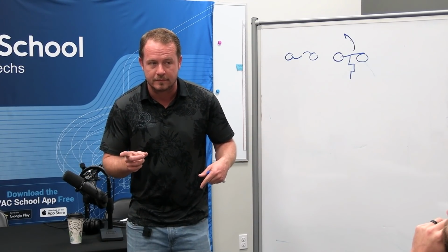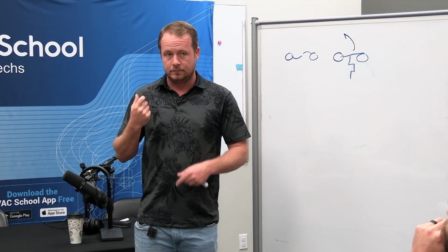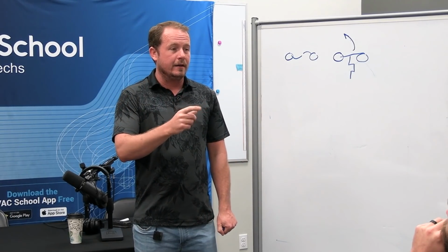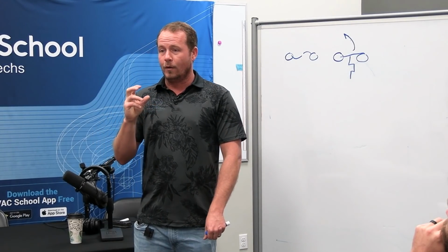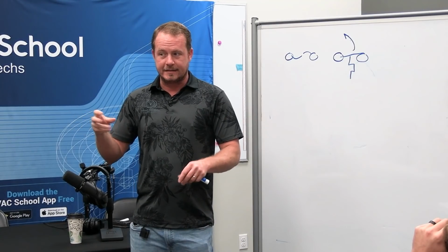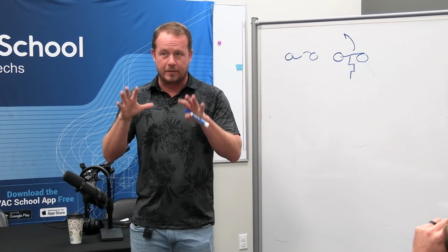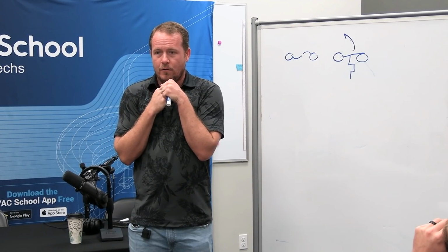What's that? Say it again. Resets. It resets. Why does it reset so quick? It's not as hot. The heat is isolated to the winding. And the winding is very thin copper wire. So it's an electrical overheat. That makes sense? It's an electrical overheat because it can't run. It's on what we call locked rotor. Compressor's bound up. And so it does this, like, no, I don't want to move.